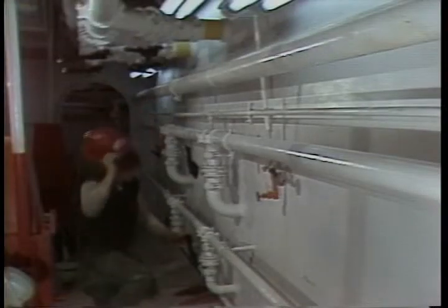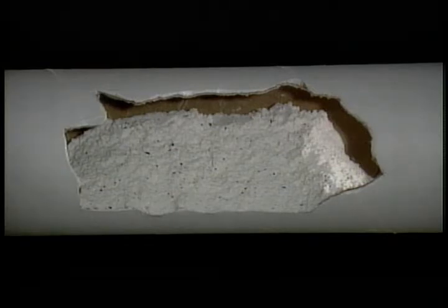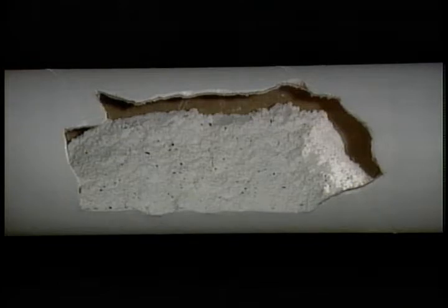Another thing that might cause clogs is the failure to purge the lines good enough after transferring product. If any bulk is left in the lines, it'll settle into the pipes and could plug the lines, especially if there's a little bit of water puddled up somewhere. That's why we've told you to purge the system for 10 minutes after you transfer.